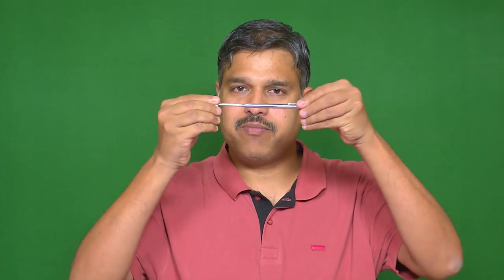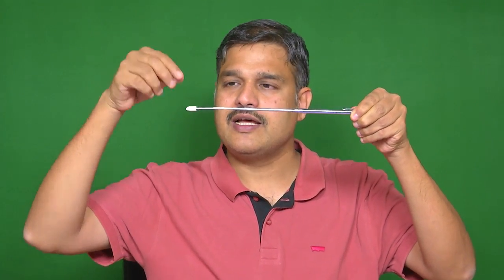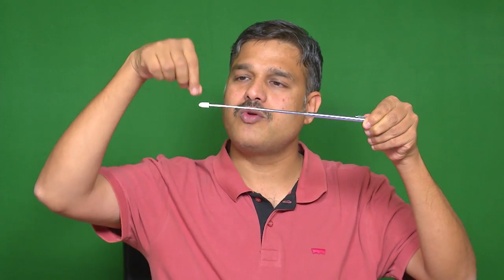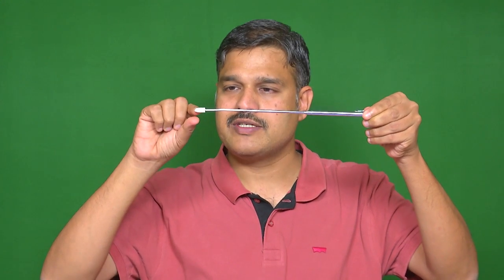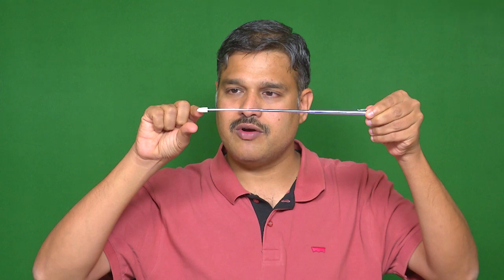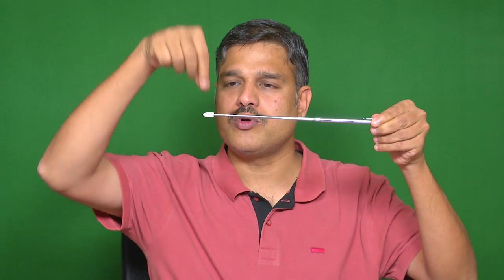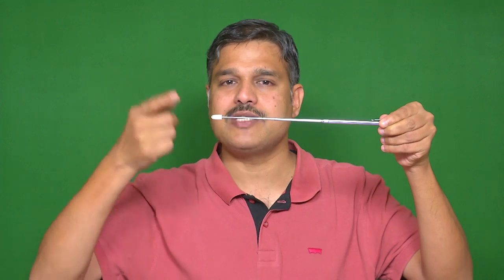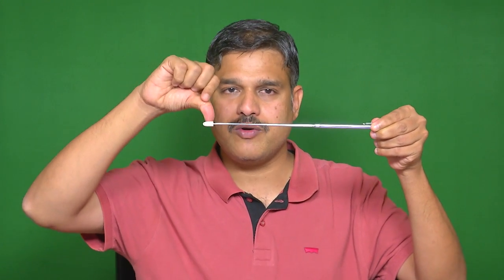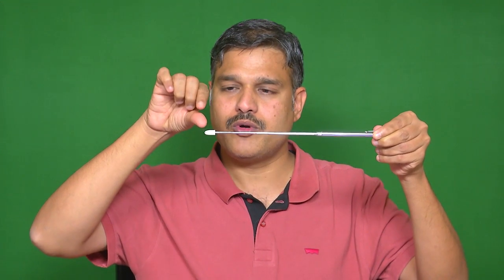The superposition principle being applicable means, like, there is a cantilever beam and I apply, say, 1 kilonewton load and it deflects, and then I apply another 1 kilonewton load and it deflects. If I add the deflection of the first 1 kilonewton load and the deflection of the second 1 kilonewton load, the sum will be equal to the deflection when I put a 2 kilonewton load. Or you put a 1 kilonewton load at the beginning, then remove it and put a 2 kilonewton load.